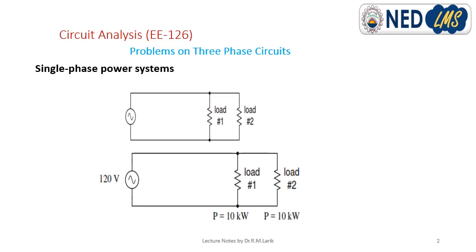Large amounts of electrical power, as in commercial buildings or industrial installations, are generally supplied with a three-phase electrical supply. The three-phase services could be either the three-wire or four-wire type. Within commercial and industrial installations, circuits would typically be divided into both single-phase and three-phase circuits. The three-phase circuits would be used to power motors, whereas the single-phase branches of the three-phase services would typically be used for lighting, heating, and fractional horsepower motors.